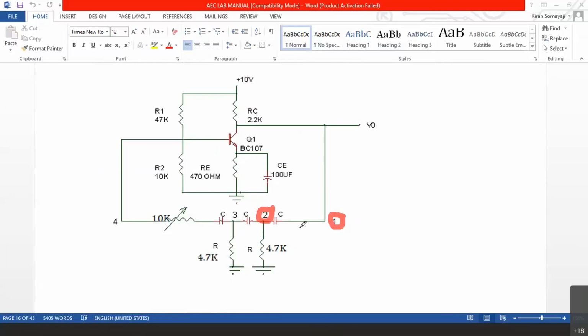As I mentioned already, they have the tolerance. Next, keep this pin 1 there only, point 1 there only, and move the other probe to point 3. Now, this will remain in that Y deflection plate only or Y channel only. You will be moving this to the X channel to the point number 3 now. You will see another Lissajous pattern on the screen, but you will be seeing it in the second quadrant now. I will show you.